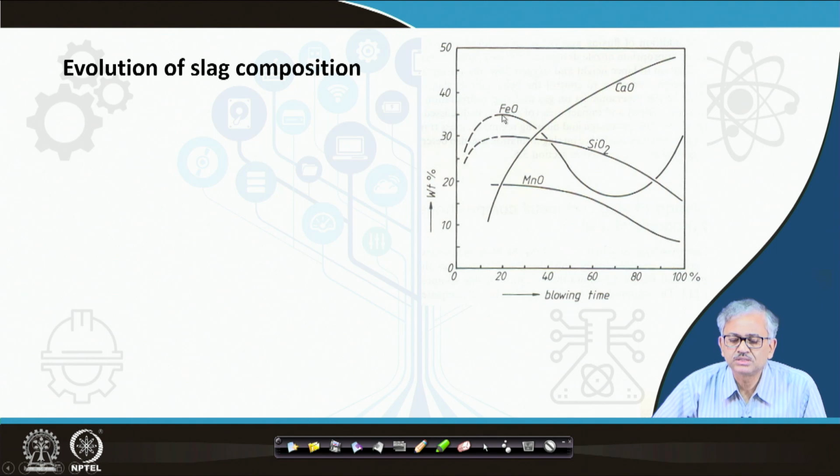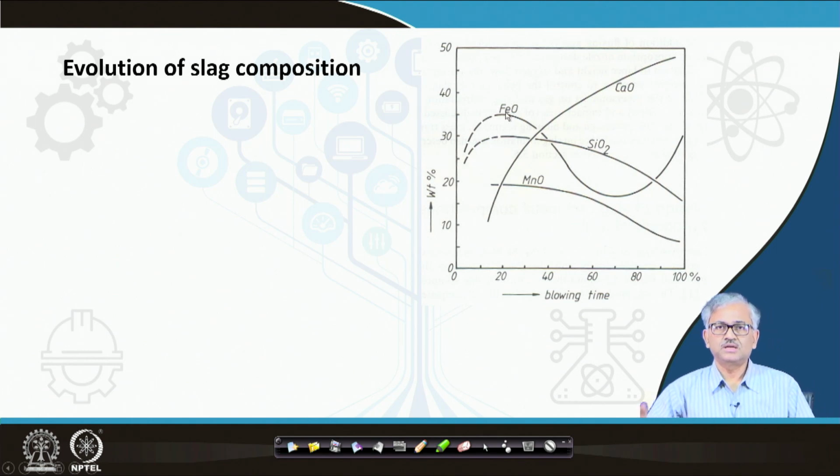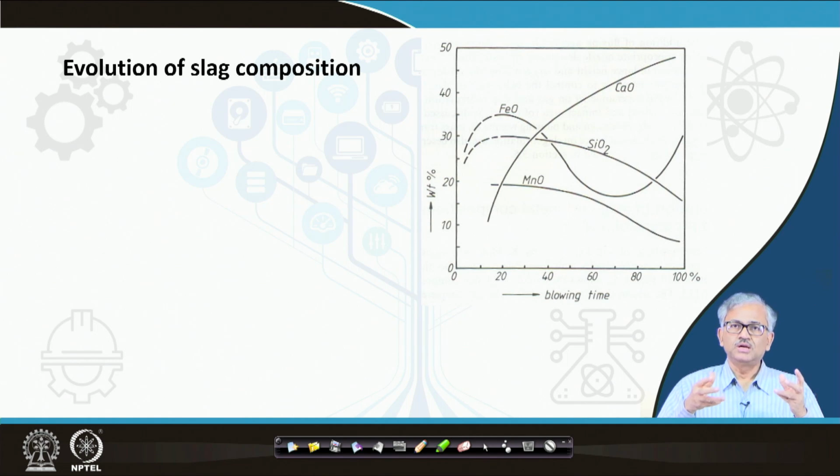So, the load on FeO is not high, that is the rate of formation of FeO initially is much higher compared to the rate of its consumption for oxidation of silicon and manganese. So, FeO gradually increases during this period. And after that, as the time progresses, when FeO is sufficient in the slag and the temperature is also high in the slag, then CO starts dissolving.